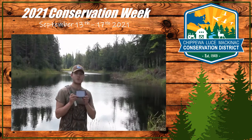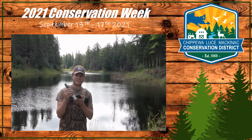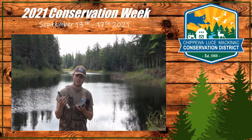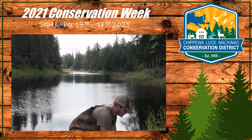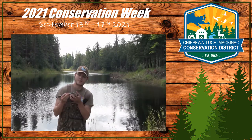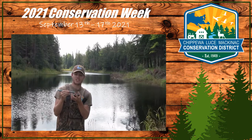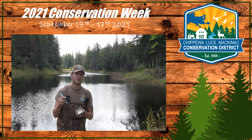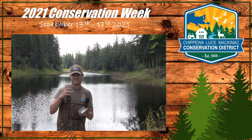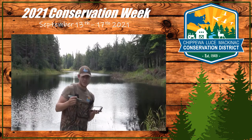We have a small unit, and with that unit we attach a probe with a sensor on it. This is the pH sensor, and the way this equipment works is there's a small sensor at the end of each of these probes, and we're going to stick that into the water. The number is going to bounce around, but it's going to settle around a number, and that's the reading we're going to take. So let's do some readings.